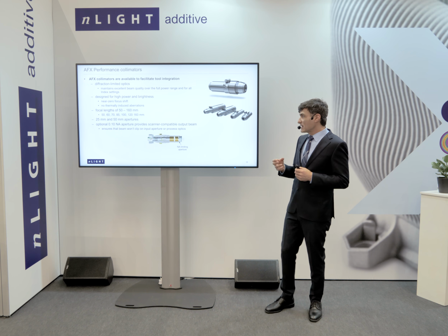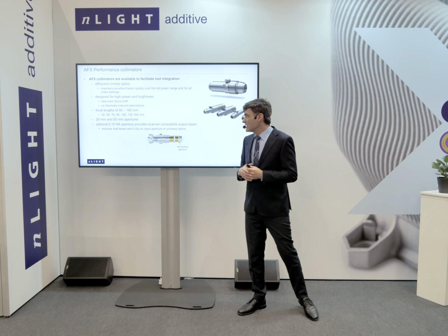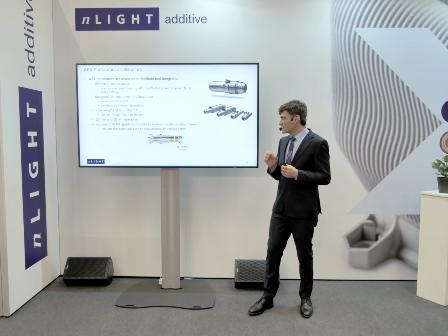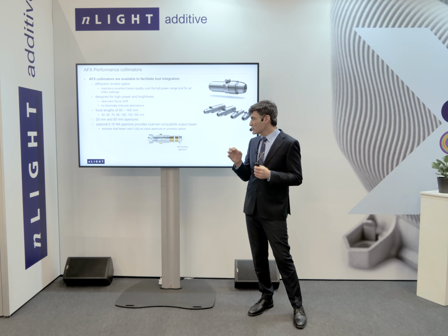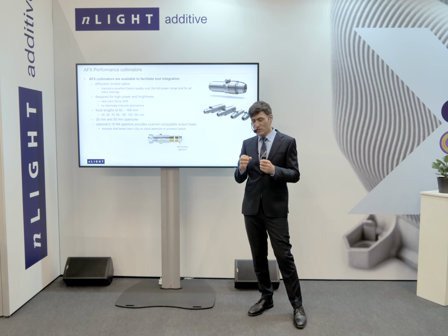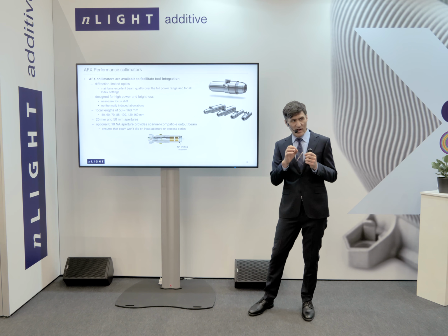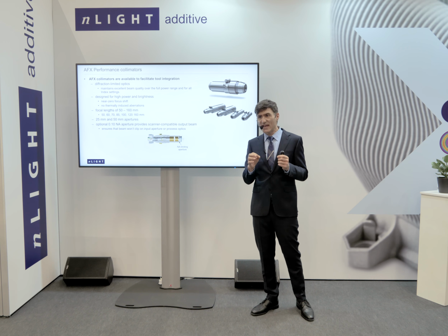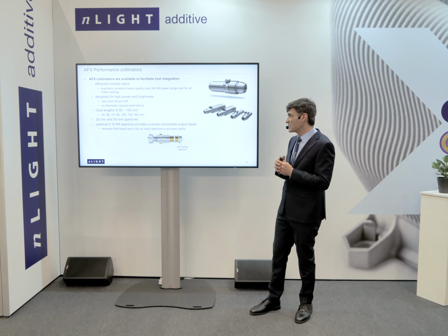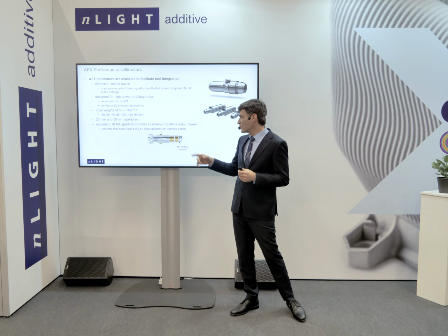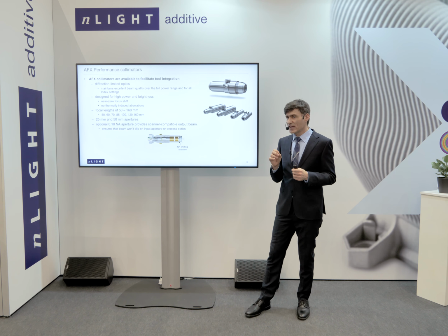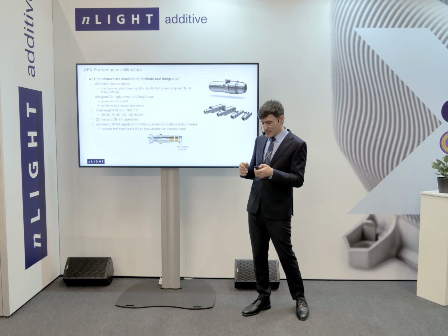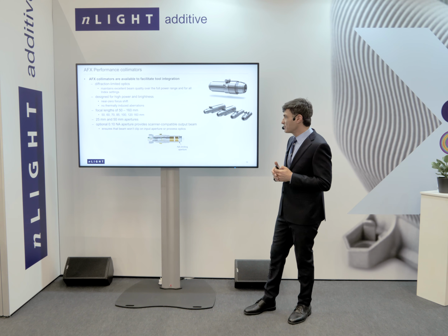We can optionally include an aperture in the collimator, and this ensures that the output is compatible with scanners. Scanners have an aperture, and the aperture and the downstream optics are very intolerant of any power outside of the NA of those optics. And so we include a water-cooled aperture in the collimator to ensure that you won't exceed those limits in your scanner or the other optics.